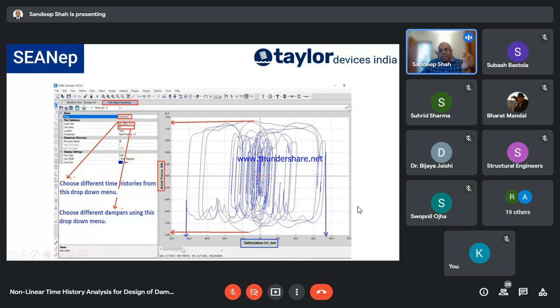Now what you do is, has your damper stroke? So over here you see a stroke of 60, and over here you see a little less than 60, and over here you see the force capacity is about maybe 1350, and over here you see the force capacity is about 1400, right? However, you are using nominal properties of the dampers, and it is producing this graph.